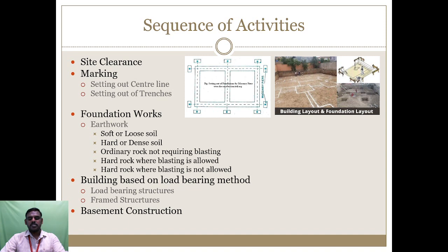This framed structure also has lintels, in a continuous manner. Now, for the framed structure basement, the bottom beam will carry the column foundations. Then we construct walls like a basement. In those base walls, inside plastering and outside plastering will be done. After that the soil will be filled in the basement area. After that the beam will be cast.